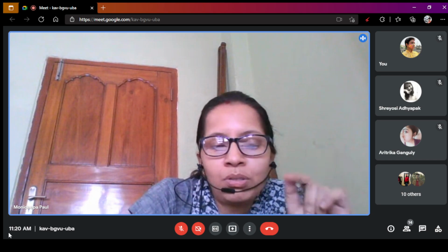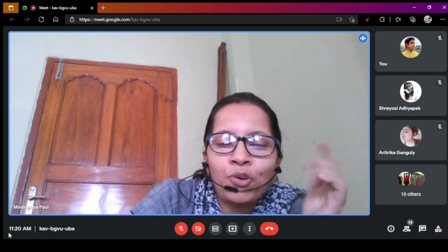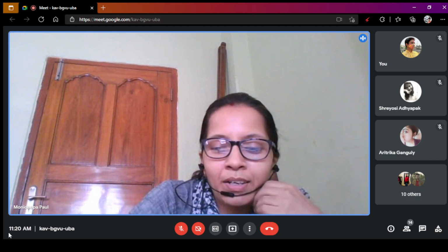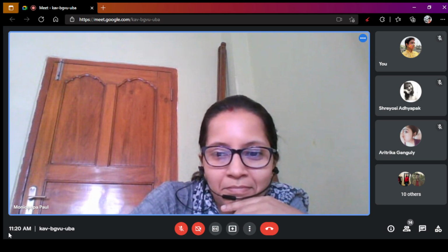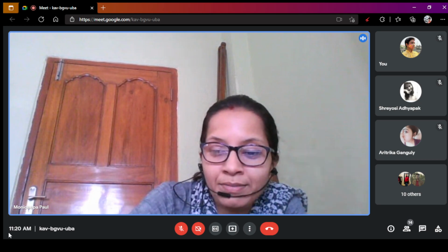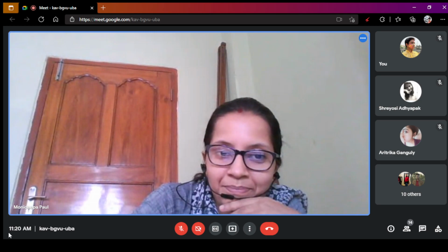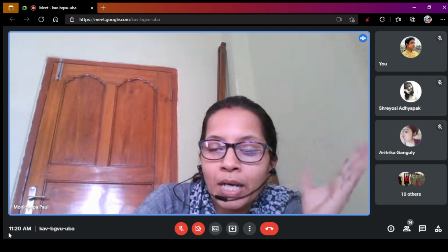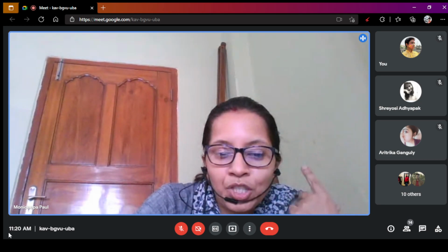From this note, you see that FET acts as a switch. So if a question comes on how FET acts as a switch, then you can write the answer. During the ohmic zone, current is flowing. During the saturation region, current is constant. During the cutoff region, no current is flowing. So FET acts as a switch.